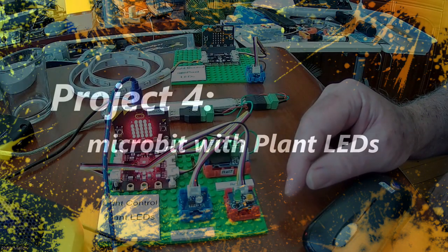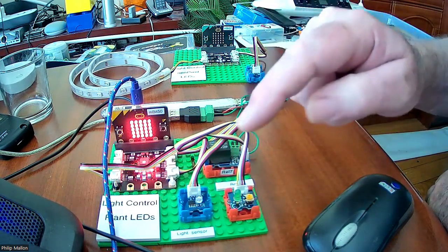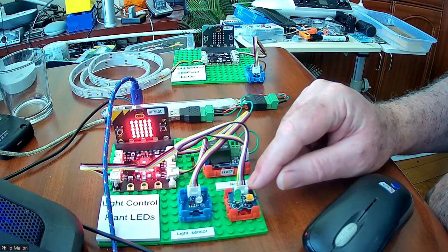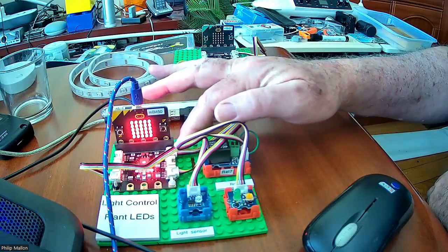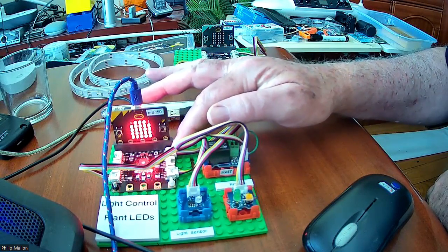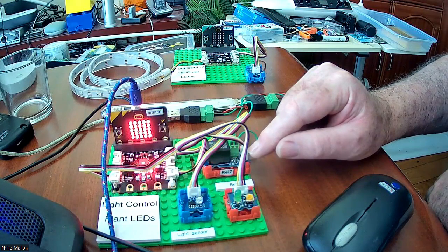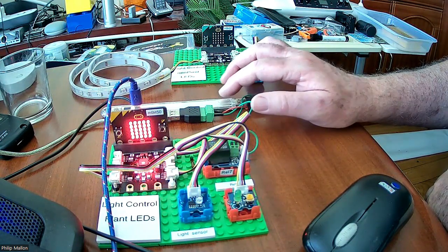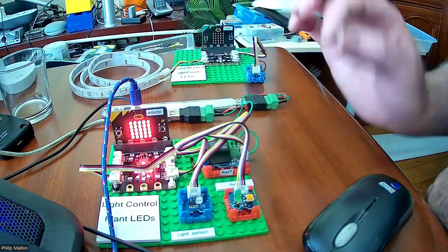This is a modification of Project 4, where we're looking at controlling plant LEDs. And what we have is an additional LED just to help with the debugging. Otherwise, it's similar to Project 4 that you have. What else we have is a light sensor, and that feeds into port 0 on BitMaker and to microbit also on port 0. In addition, on port 16 over here, we have a connection to a relay which switches on the contacts for a USB-powered plant LED light. So this has already been preloaded with software, and what I'm going to do is just demonstrate it.